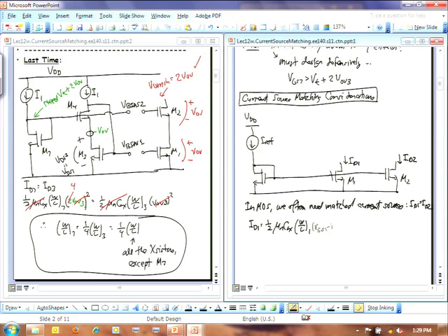In an IC process, that's something we're just not going to be able to get away from. We will always have these finite fabrication tolerances. Technology does get better with time, but so do our devices. We still get smaller and smaller channel lengths, so our technology is unable to get exactly the dimensions we want, and unable to even match two transistors side by side. So you're always going to have some mismatch there.